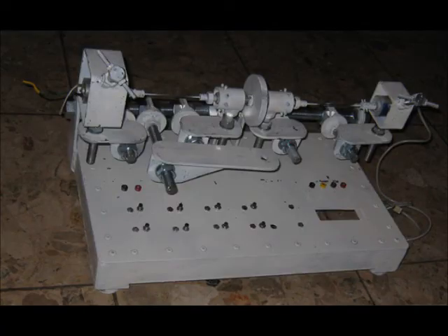The mechanical setup is built in my workshop at home, so there are no turned or milled parts in it. The challenges are to make all parts adjustable to face the low precision and to reach a high stiffness to get a high resonance frequency. I arranged threaded rods as a Cartesian coordinate system to reach the adjustability, and I start with thick threaded rods which become thinner with the distance to the mounting plate to reach a high resonance frequency.